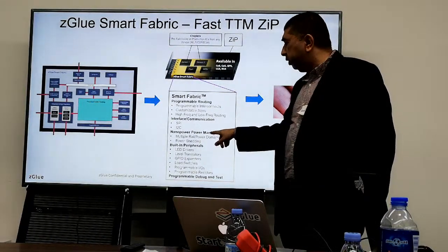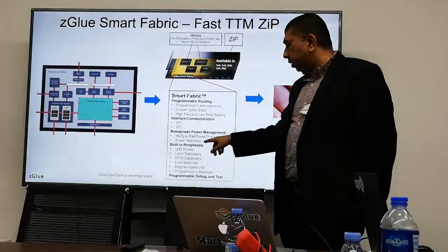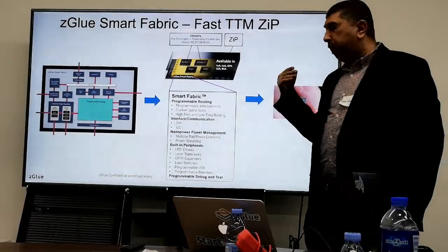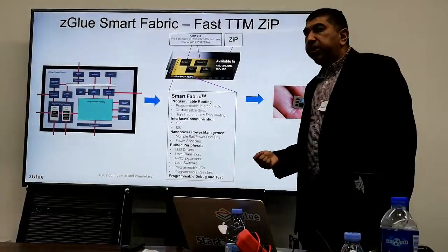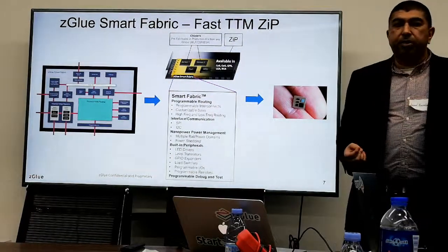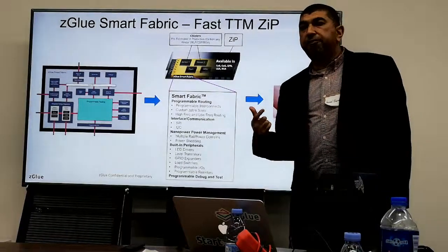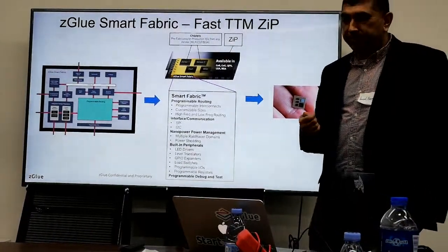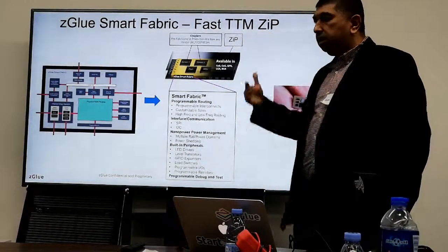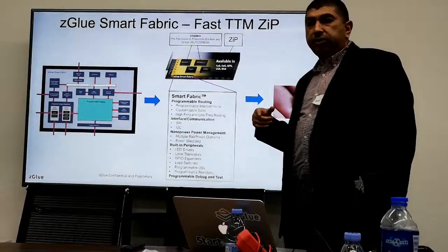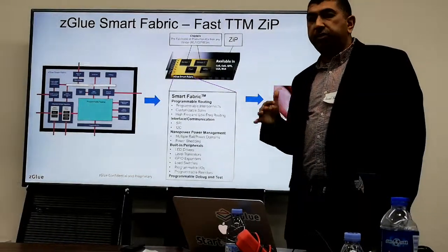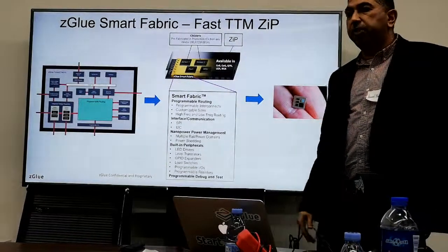battery management options. And then we have the ability to use push button controllers, LED drivers, GPIO expanders, programmable IOs, and programmable resistors. We do have a few programmable capacitors. So for termination of signals, where you need parallel resistors or serial resistors, we have that built in, and we can get to within 5% of the defined value by using a trimming methodology.